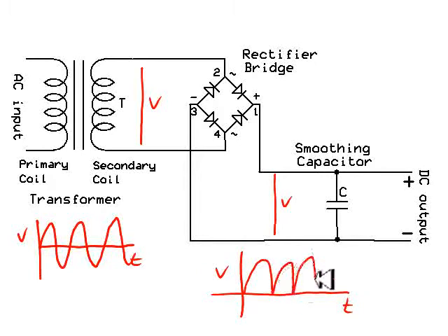One way we can think of what the rectifier bridge is doing is that every time the voltage tries to go negative, effectively the rectifier bridge is simply switching the wires. So when we have this and it tries to go negative right at this point, it just switches the wires and we get another peak, positive voltage.